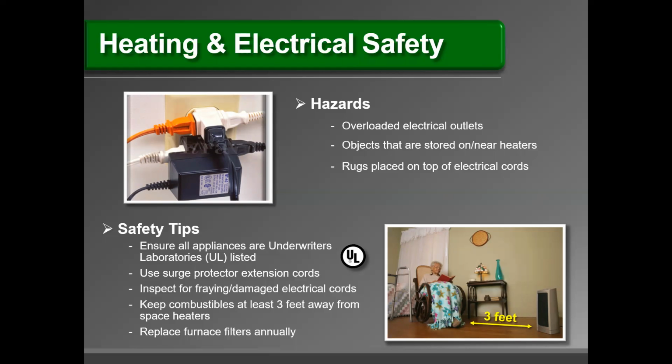And you want to make sure that you don't daisy chain them, which is plugging one into another, because that's kind of overriding its safety component. The thing that's in there is a breaker fuse. You want to make sure that you get one with a breaker fuse. Occasionally they're just extension cords and they're not surge protectors. So make sure it has a surge protector, which has a fuse in it. And then a lot of people think, oh, it protects my electronic equipment, but it works the opposite way.